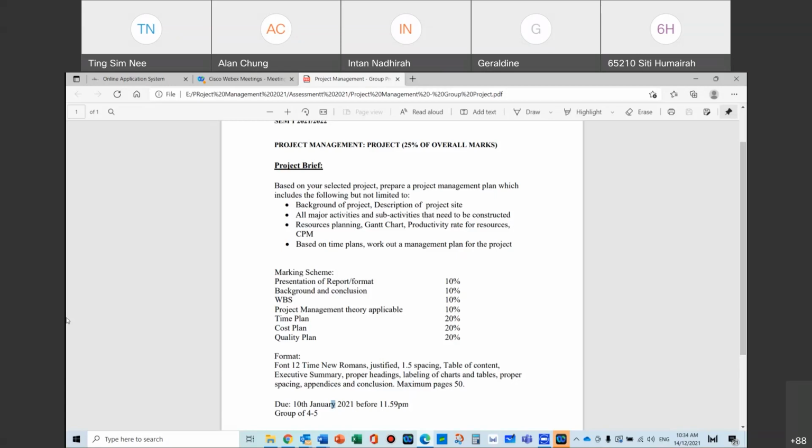So just watch out. If you want to split, make sure that in the production rate, you factor down the machine production rate a little bit. It's all about you being careful or not careful. Then, if you do split it up, just make sure that you do the calculation properly. You don't double calculate these two things.